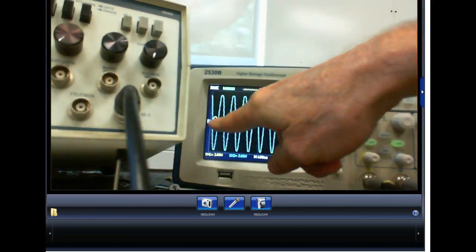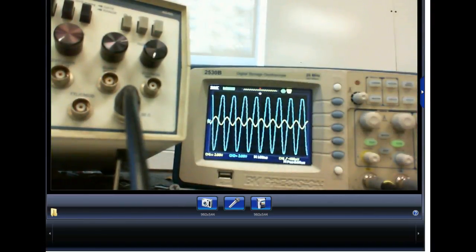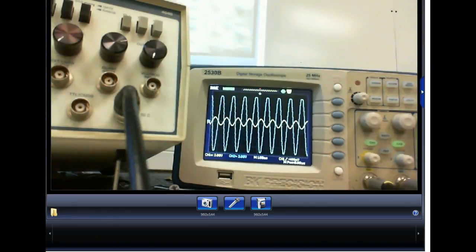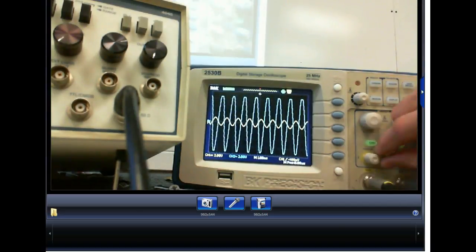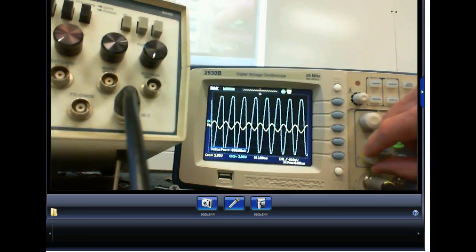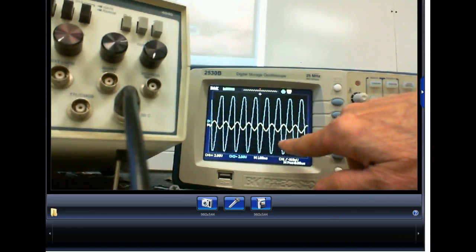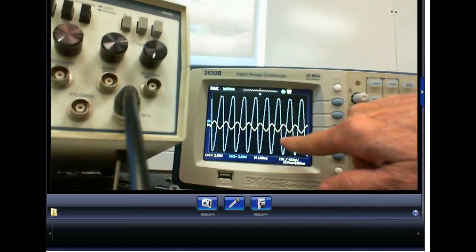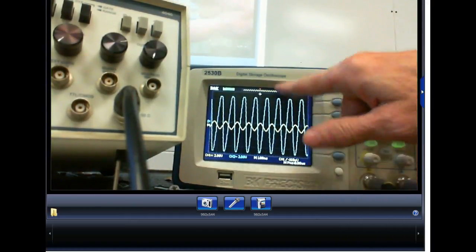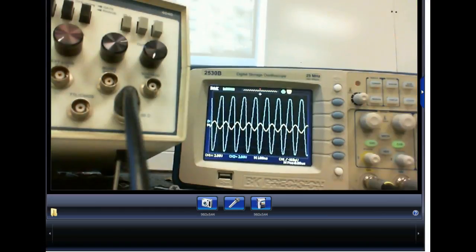And this is on my base coming in. This is on my base input, which would be on the other side of my capacitor. And then the blue one is the output. They're both set to exactly the same range, 2 volts per division. So roughly we're putting in about, of course, if I wanted to measure this, I would get more accurate. We're putting about 1 volt in, and we're getting 1, 2, 4, 6, 8, 10, 12, over 14 volts out.